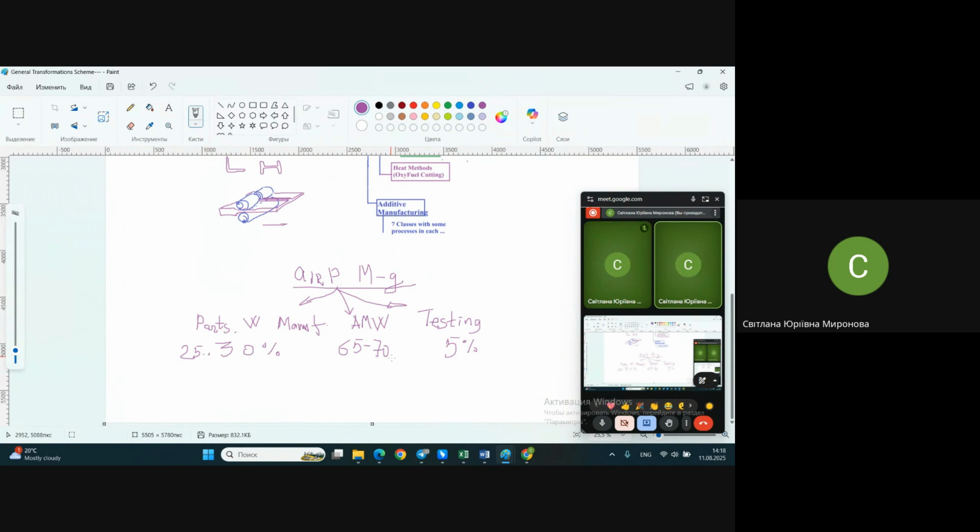Well, parts manufacturing. And here we have shops. Why is it divided like this? Because now this technical system for aircraft manufacturing is divided on a principle mostly not by kind of manufacturing... For parts manufacturing, it's division by shops based on kinds of manufacturing, mostly, as I said. When it comes about assembly and testing, it's already another principle of dividing the shops. It's the so-called aggregate principle.